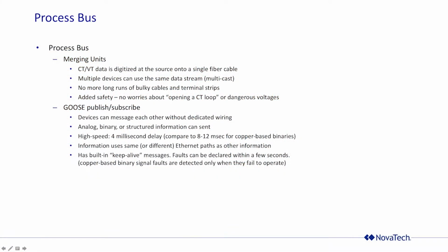What's wrong with long wires on a CT? You have more impedance. The higher the impedance, the higher the burden on the CT, the higher the chance of CT saturation. CT saturation is very bad. There's also the chance, because you run it to all the devices within your substation, that one of those CT wires can get loose and break. And when that happens, there's a term we use in the engineering industry called explosion. Very, very bad things happen. You will destroy something. If you are lucky, you'll only destroy one device, but that device will be turned into a piece of charcoal. I guarantee that.